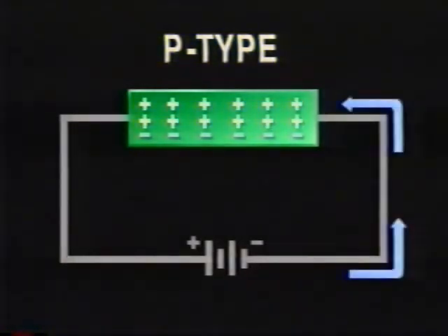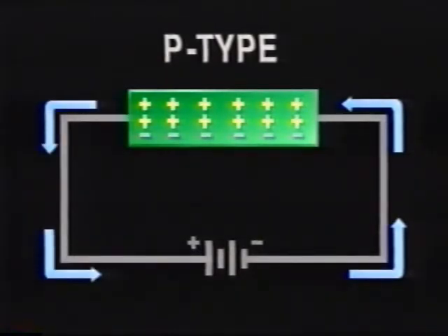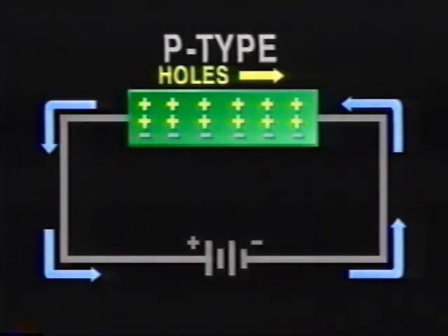In P-type semiconductors, the valence band holes that are produced by the doping process far outnumber the few free electrons that are the result of thermal energy. As the electrons from the voltage source enter the semiconductor on the right, they fall into the valence band holes and move through the crystal from hole to hole as valence band electrons. As they exit the crystal on the left, they again become free electrons and return to the voltage source. Once again, the holes appear to move from left to right as they are attracted by the negatively charged electrons entering the semiconductor.